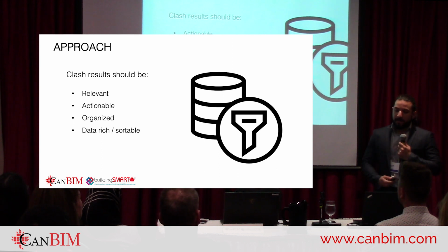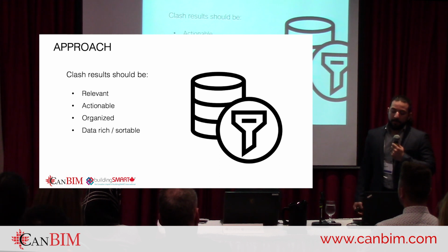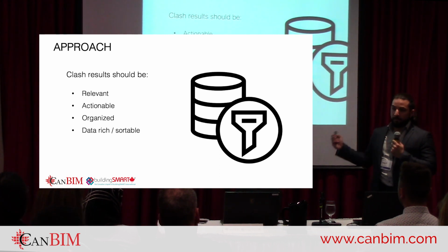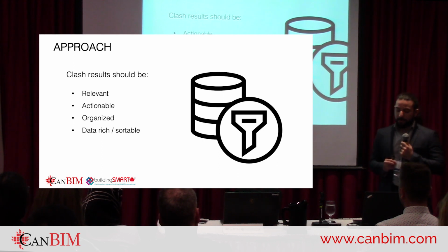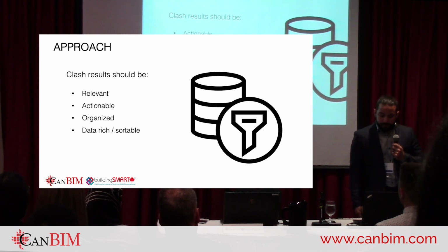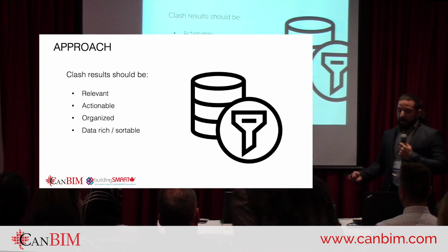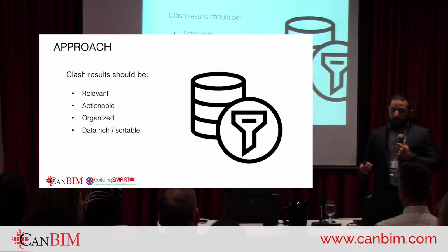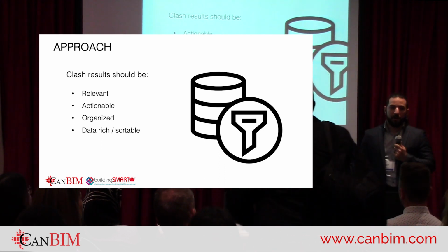If you end up doing flat CAD exports, for instance, that's not going to give you very valuable data. So you can export your data in several different ways. The more information you have, the better results you will be able to get from this whole process. The data in your models will really allow you to sort through the items and find exactly what you're looking for. And you should always use formats that carry data, like NWCs, IFCs, or whatever format that basically can contain more properties than just geometry in your model.